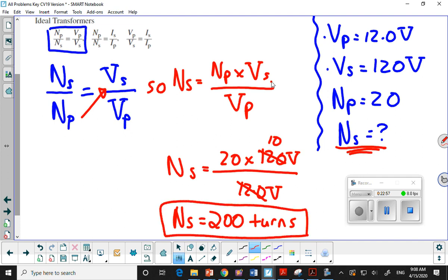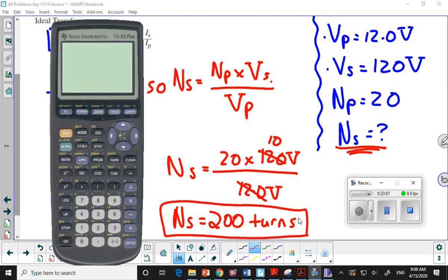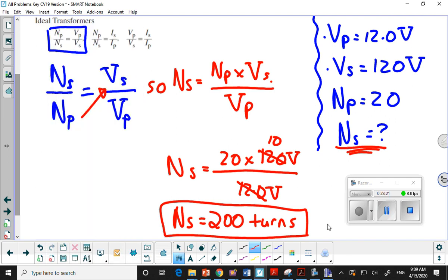If you would rather use a calculator on that, we'll just plug that in: 20 times 120, enter, divided by my 12, before I did my cancellation. And again, if you weren't sure of that, there you have your 200 turns in the secondary. So take a few minutes, copy that down, hit pause.